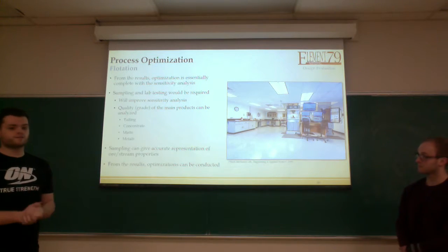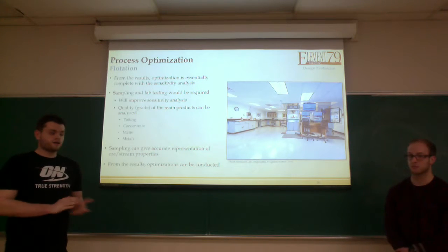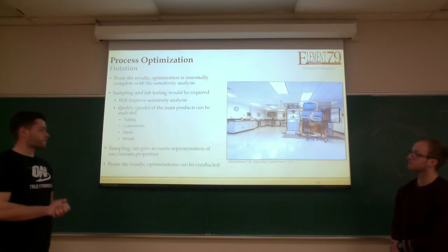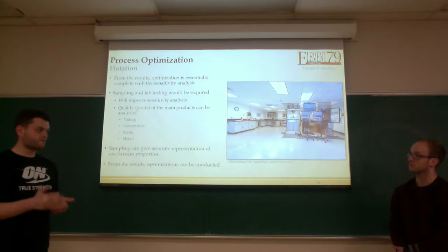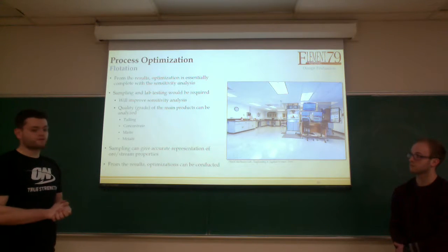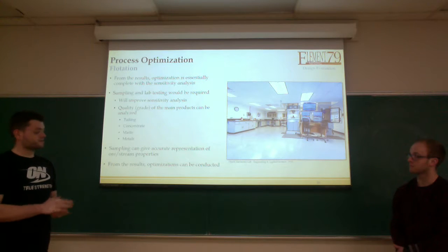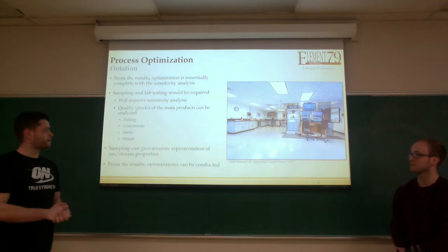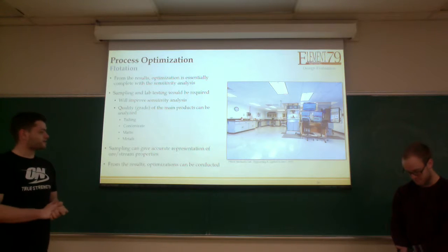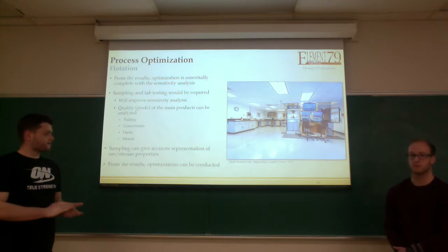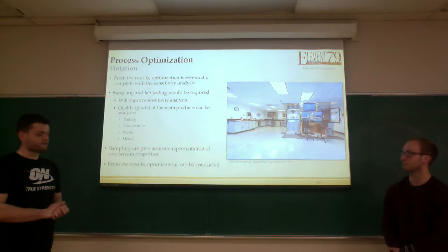So for flotation, as previously mentioned, lab testing would be optimal for creating an optimization. Right now, the process is optimized to about 89% efficiency with a 25% recycle stream, which is higher than our goal of 86%. However, with testing on tailing, concentrate, the mat, and the metals in these different streams, optimization could be done to make this process more efficient.